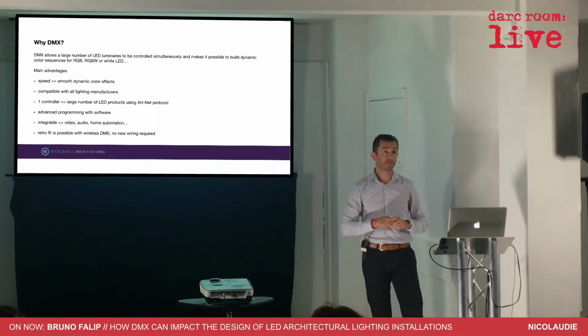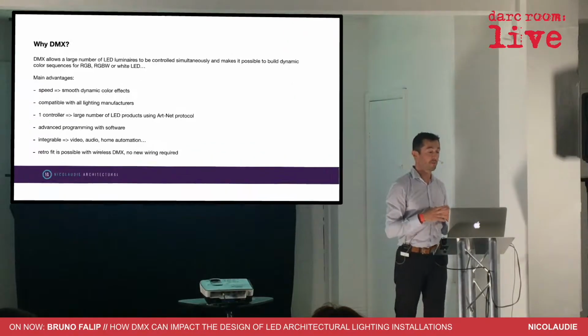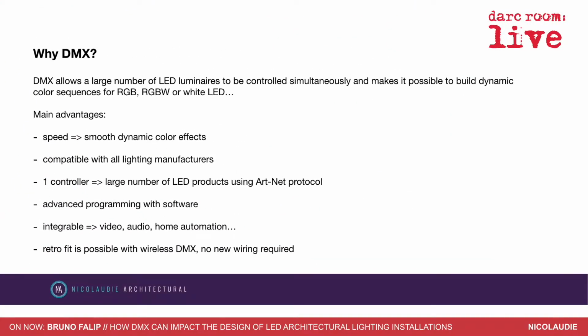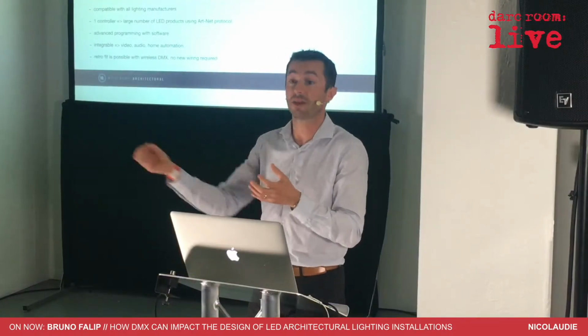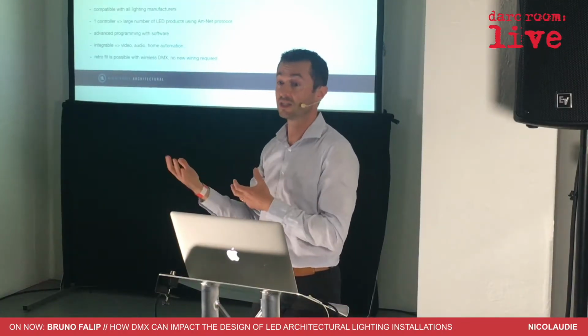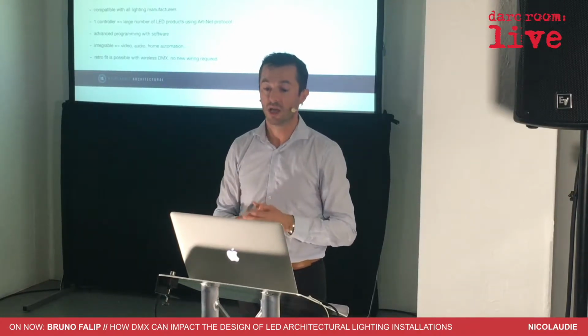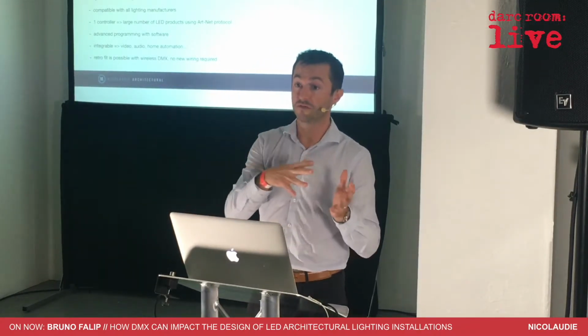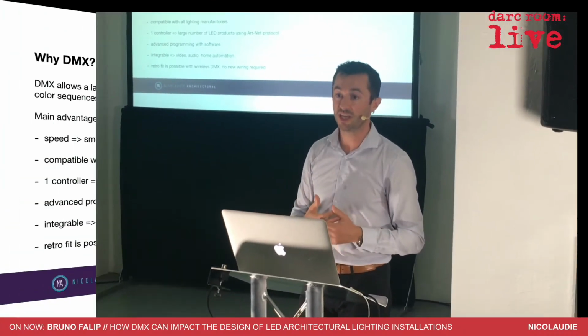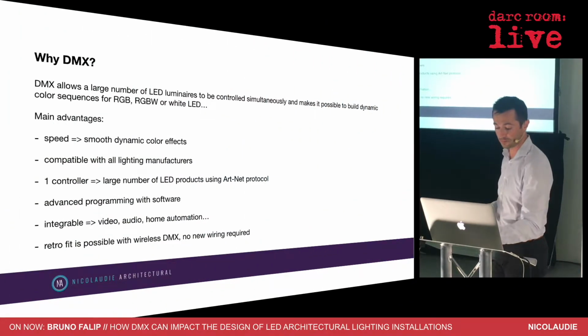And last point, retrofitting is possible with the wireless DMX solutions. There are some wireless systems that work perfectly, and imagine, again, I remember I said the problem was the wiring. So when you get to an install that is already in place, the problem is carrying the DMX somewhere. With wireless DMX, this is now possible, as long as the power is there, to retrofit the install and move from standard lights to a DMX compatible light.